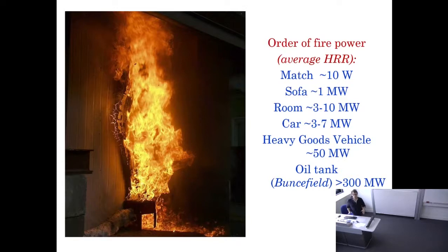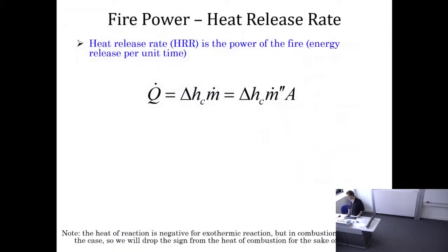You have to use foam, which not only carries the water and takes the heat by being vaporized, but actually creates a layer that avoids the oxygen arriving to the liquid. That is what the foam does, and then it protects it somehow.